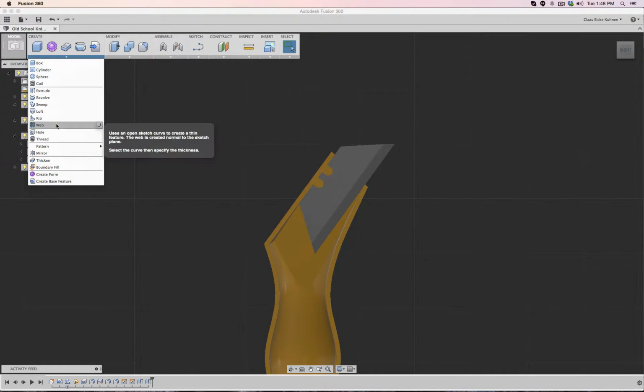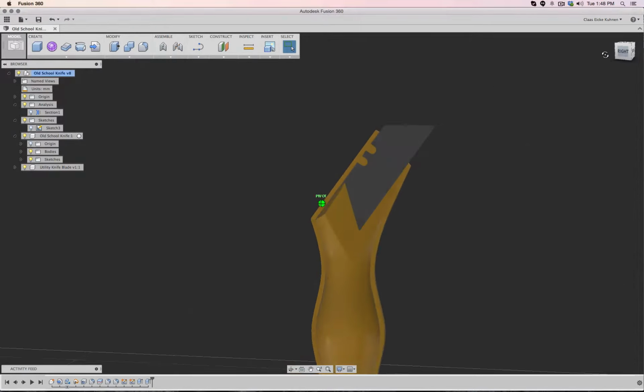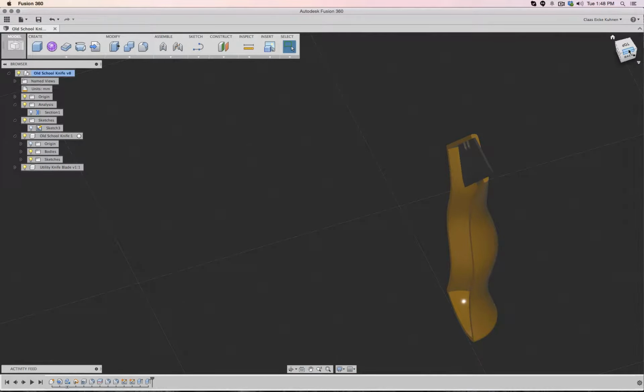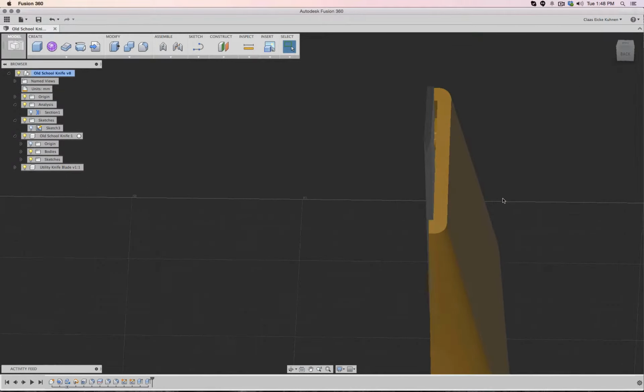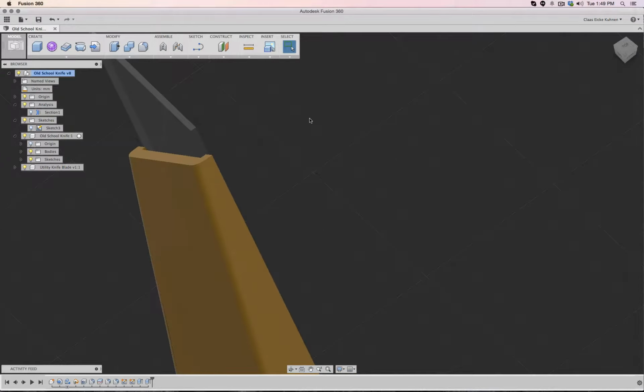So to create the web, or for example the rib function, we need a planar sketch. And of course, the question you have to ask yourself is: do you want this one to be flush with those corners, or do you want those ribs already to have half the distance of my blade, kind of like an offset to the inside, so where we start creating those ribs, the blades will perfectly rest on it? So we can maybe do that.